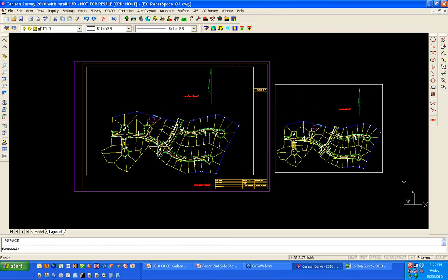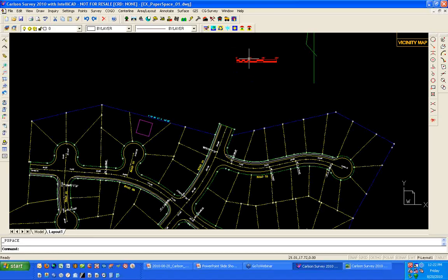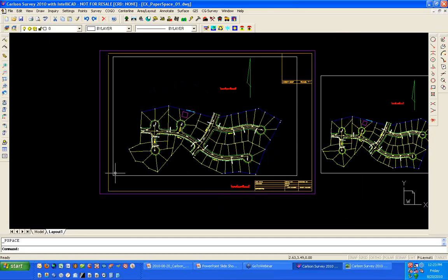But we've already talked about how we know that this building is 50 by 50. We know that from here to here on our bar scale is 50. When we plot everything inside of our sheet, our plot scale will be 1-to-1, because remember, this title block represents our sheet of paper. So you plot it at 1-to-1, but we need to have all of these entities in our drawing scaled so that 50 feet equals an inch.